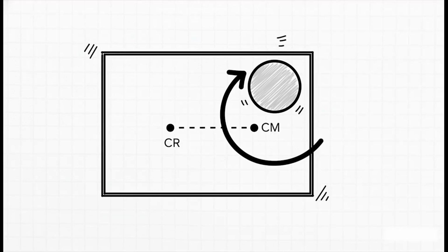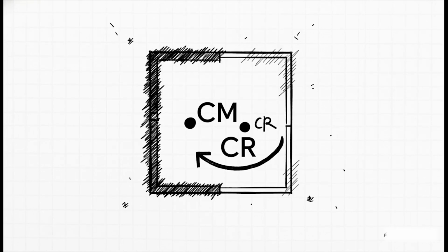First up, mass asymmetry. And a classic example, you see this all the time, is putting a huge, heavy water tank on the corner of the roof. That 120-ton load pulls the building's center of mass way over to the side. It creates this perfect lever arm, and when the ground starts shaking, that offset forces the entire building into a dangerous spin.